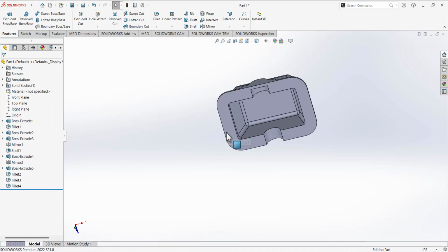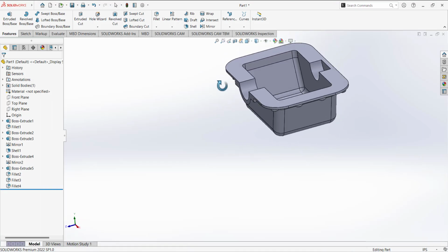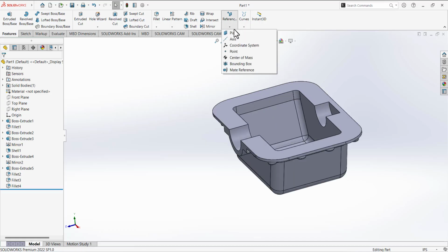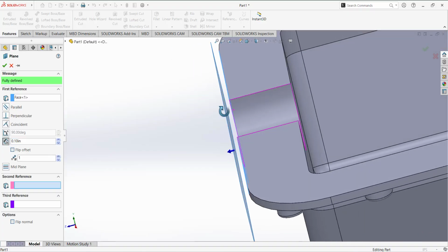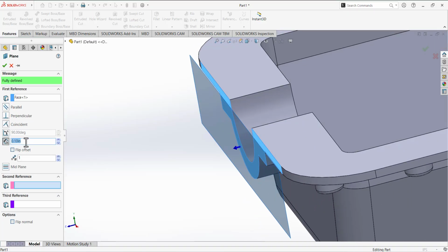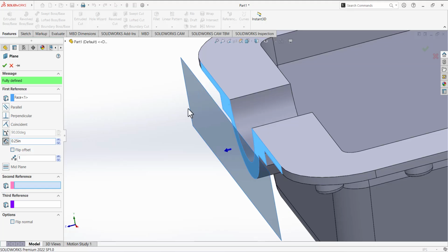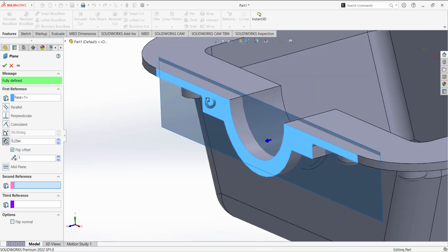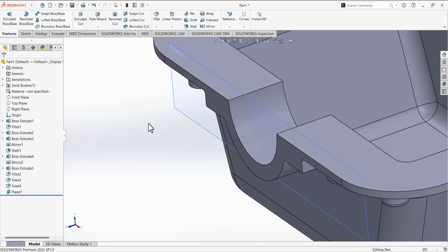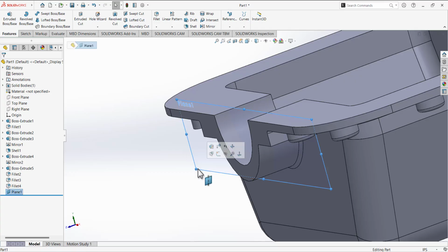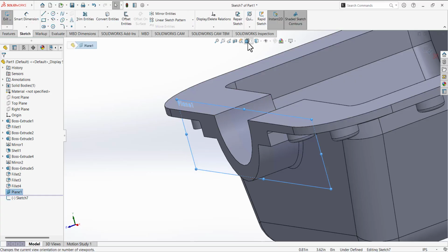So a simple circle will be needed, but we needed to shift our plane. So go to the reference geometry and select this face. We want an offset plane from this face, and here we are going to define this dimension. So it's 0.25 from this edge, this face, and in the inside. So just flip offset and make it inside to this object, into the model.